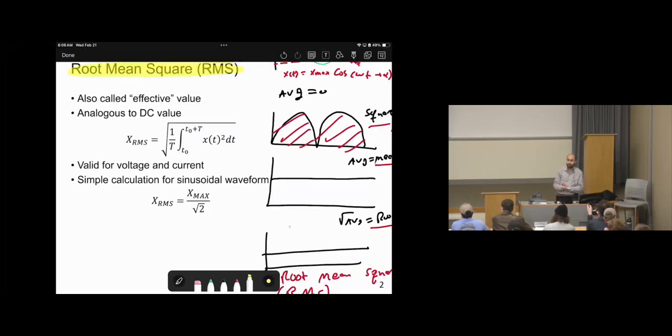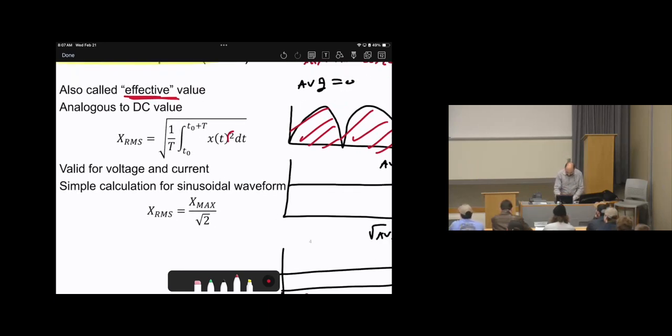That's why we are using RMS, not the average value, because we want to find something like the average, but the average is 0, so we use this value, which is called RMS. Some other textbooks call it the effective value, or the DC value of the AC. The AC is a long waveform, or a long equation, but we can find an equivalent by using the RMS. For the RMS, we see that there is a square, then there is the mean, like by doing the integral, and there is a square root. So this is root mean square.